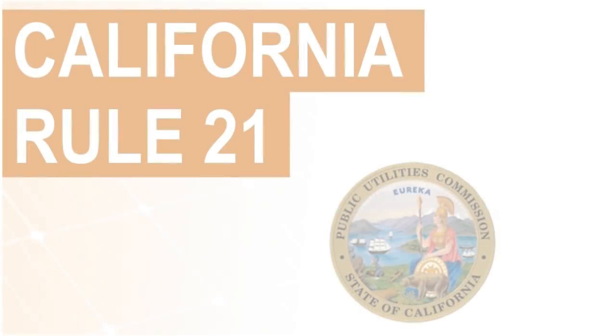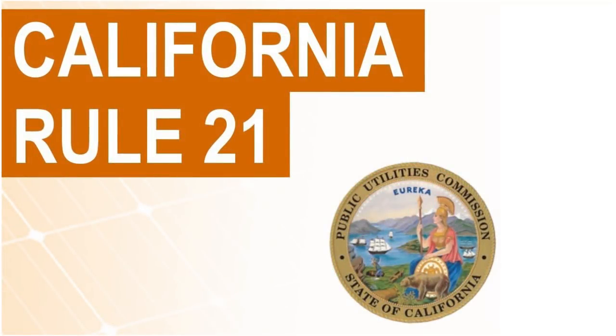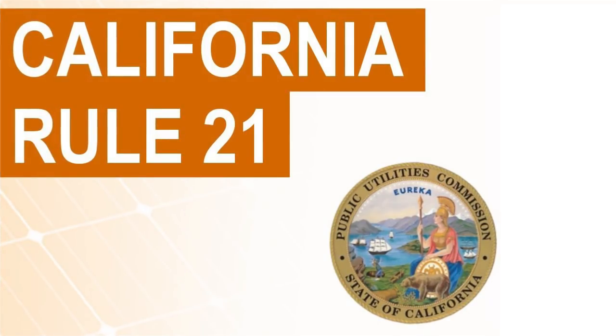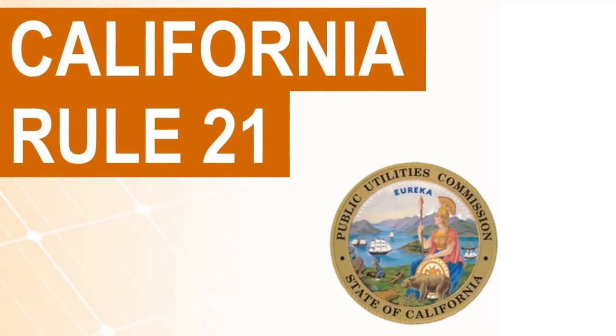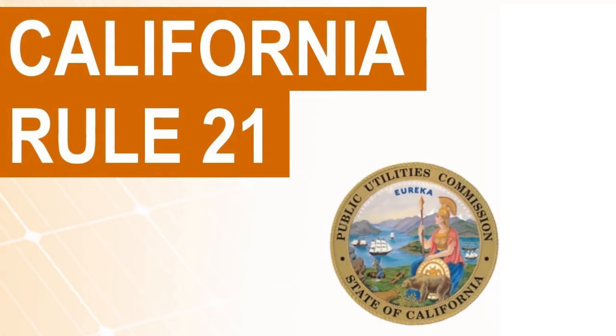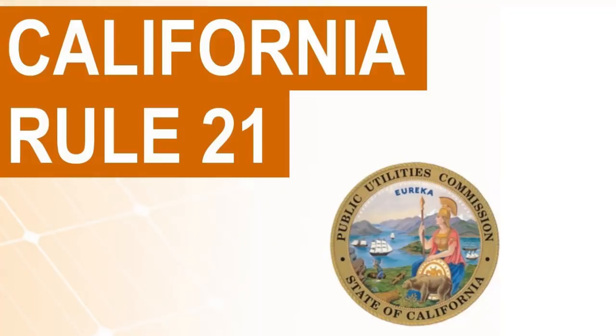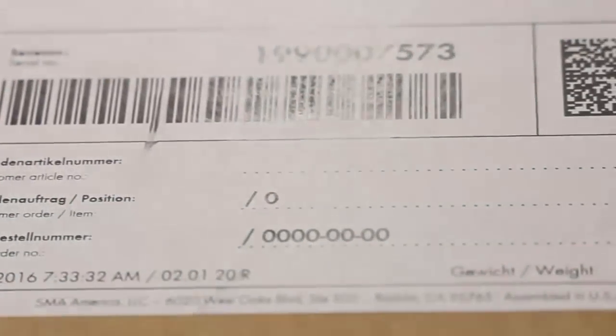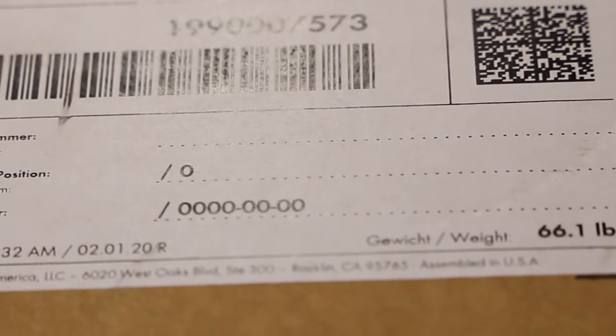Starting in September 2017, certain California utilities require that PV inverters installed in their territory have several autonomous grid support functions enabled. Equipment listed to UL 1741SA is capable of meeting these requirements, but the specific functions must be enabled upon commissioning. Correctly enabling all the functions required for compliance is as simple as downloading a configuration file to the Sunny Boy US.